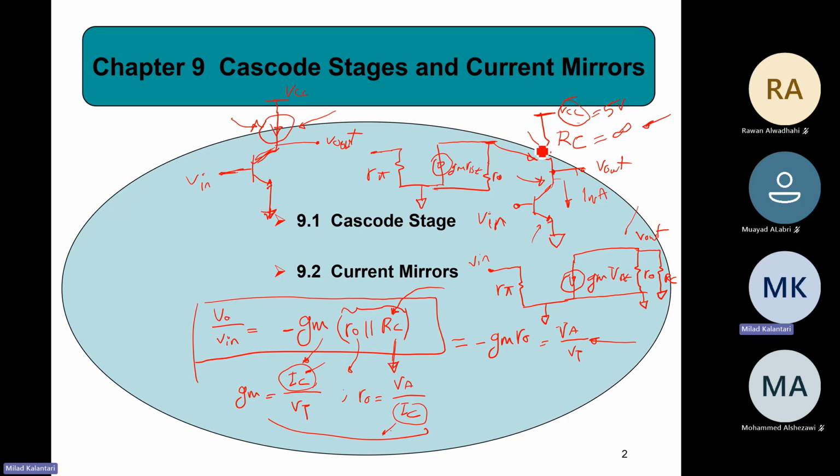But the resistor has it, right? Once you have some certain value of the current, then the voltage is already known. But for the current source, basically, you don't have that much of a limit. The voltage at the collector can be anything, but it still can provide the current, right? So this does not have the DC problem. At the same time, it has the highest impedance for the collector. And then if you could really put this current source basically here, you can reach the highest gain possible, right?